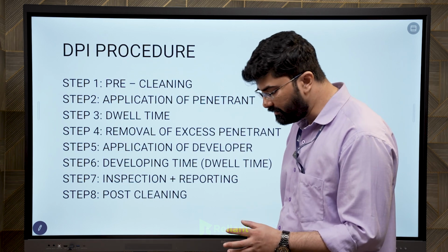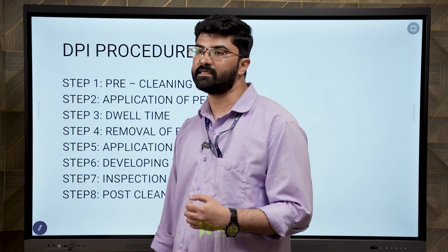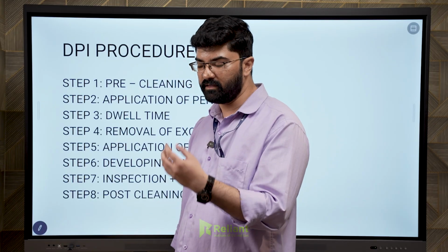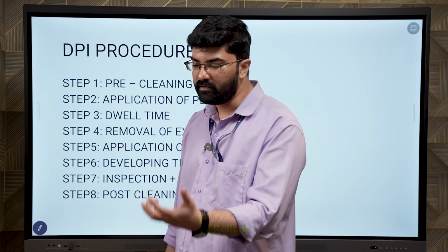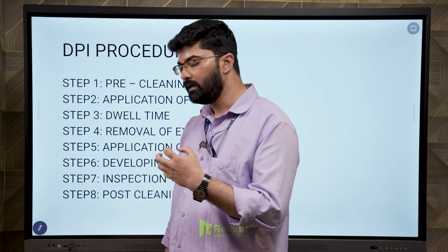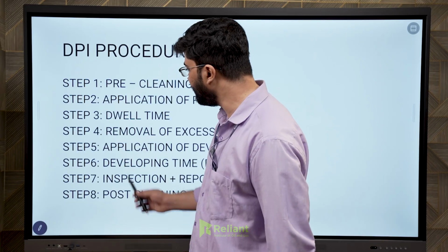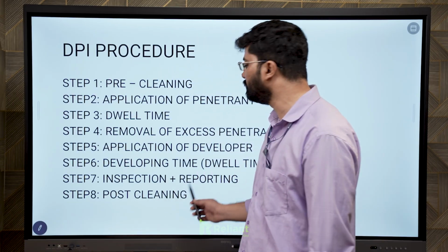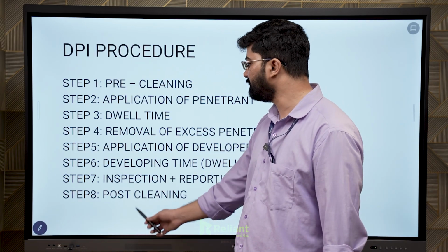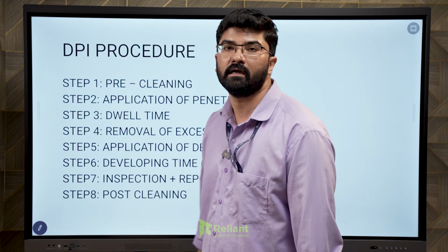When we talk about inspection, testing plus evaluation, we get the indication visibly, with the help of our eye we are able to see what type of indication, we justify that, and then we evaluate whether to accept, repair or reject. With that, inspection concludes, and then we have to do the reporting, and finally we have to conduct post cleaning and return the piece to the client.